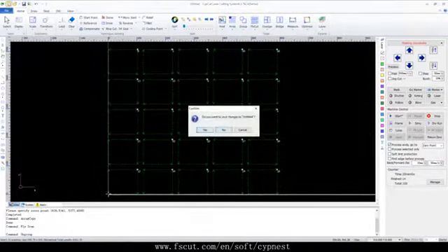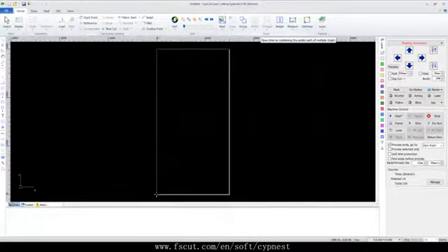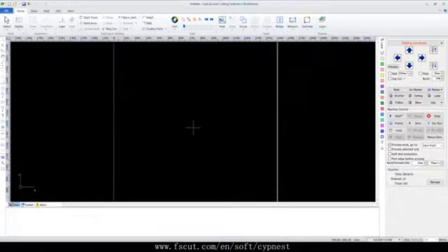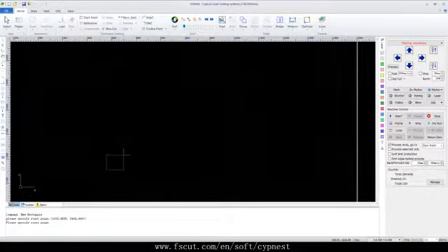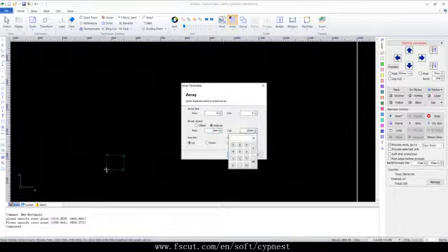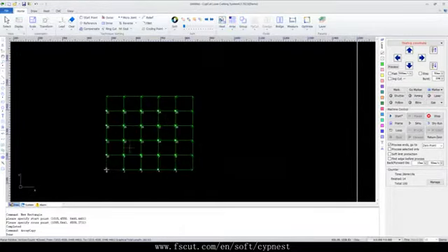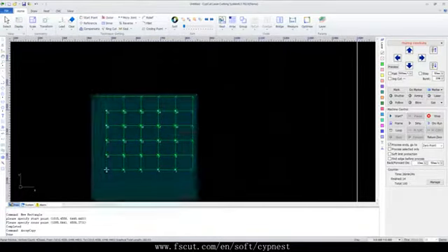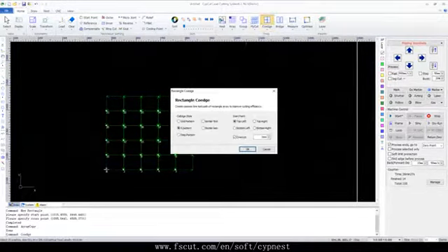And what is Coedge? We combine to generate a shared edge between parts with an overlap edge, so as to eliminate unnecessary cutting path. Cypcut supports Coedge for rectangles without rounded corner. After we select the graphic and click the icon, there will be 5 ways of Coedge to be chosen. Let's take one for example. We recommend overcut as default setting.